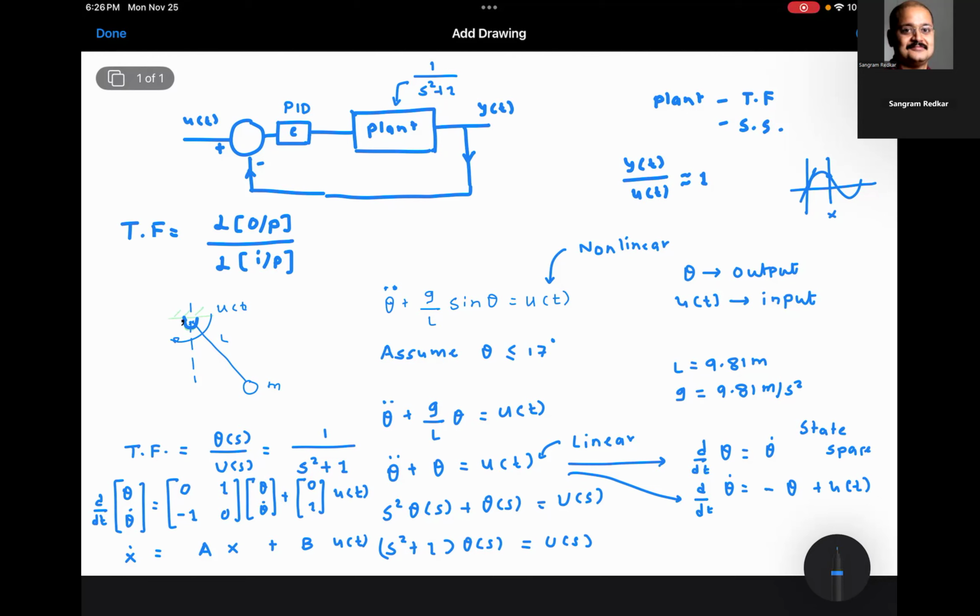Tuning PID controls is most of the time trial and error, but there are heuristic rules and algorithms that you can use to come up with a good PID control that fits your specification. I'm going to show you how to use the MATLAB Auto PID Tuner to tune the PIDs. That would be the first part.